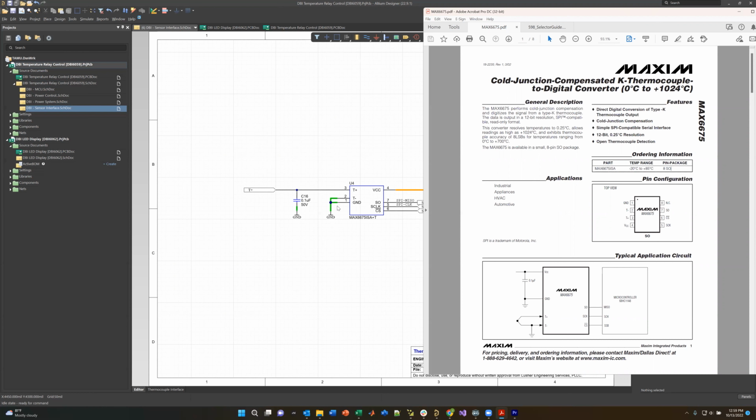And the voltage is related to the temperature at which they're exposed at the junction. So you have to know that, and of course the junction temperature at which they come to the device to be read is incredibly important to know. And then there's a very non-linear function that converts this to Celsius. That's all being done internally to this chip. So we get Celsius as an output.